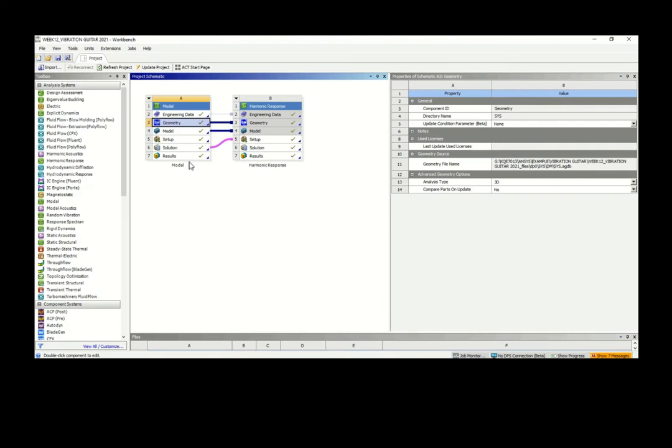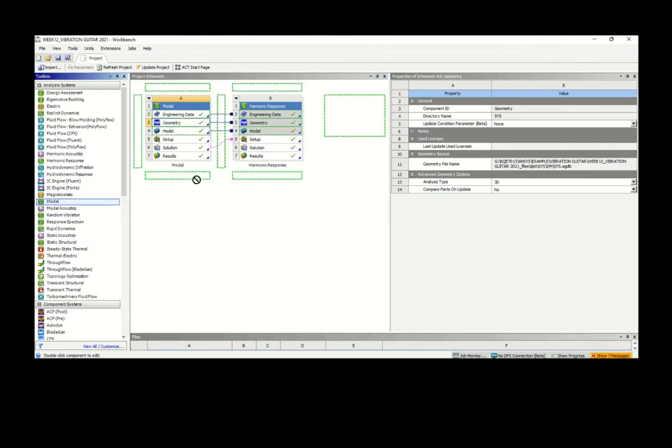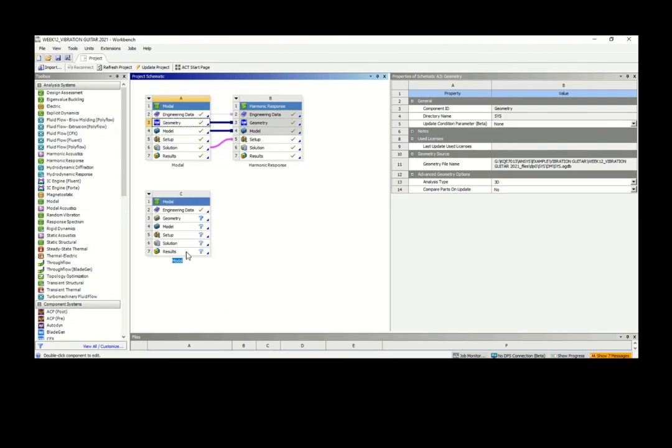To perform this particular case study, first you have to perform modal analysis. Just remember the flow. You perform modal analysis, you get the modal parameters or the dynamic characteristics in terms of natural frequency and mode shapes. Then only you use this to determine the response. Here we are talking about the harmonic response. So first you have to perform modal analysis, and you get your natural frequency and your respective mode shapes.